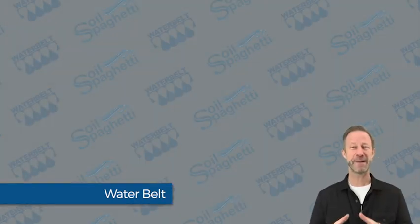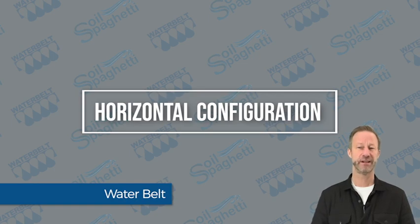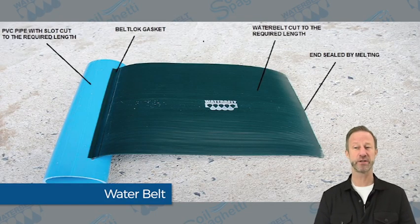There are 3 main assembly configurations designed to suit different application requirements. The most common assembly is the horizontal configuration. With this assembly, belts are installed into a collection pipe with the spacing and lengths of the belt chosen for the type of soil and the severity of the water conditions.